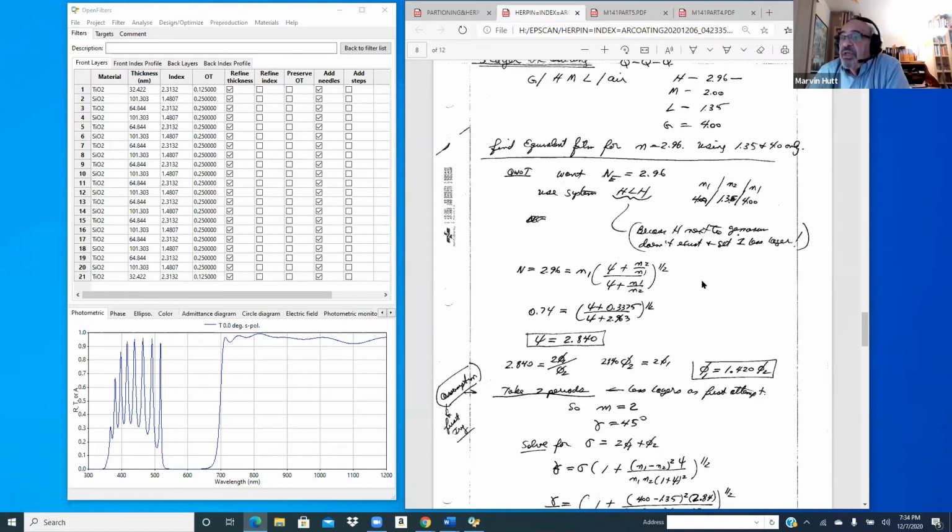So using HLH, that's 4, 1.35, and 4. Because, of course, look, the H next to the germanium doesn't exist and gets 1 less layer. In other words, if I take this and I make this a high, low, high again, the high will make this layer thicker and it'll coalesce into 1 layer, right? I'll have 1 less layer.